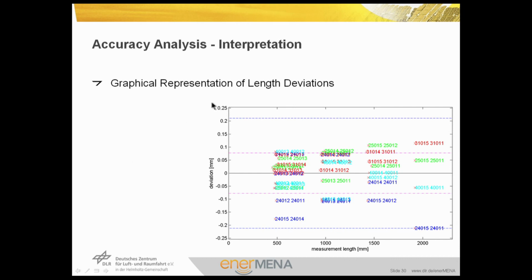The graphic on the lower right shows the distances for different points together with the mean and maximum value. So for the particular measurement shown here, the maximum deviation is in the range of 0.2 millimeter, so the overall measurement accuracy should be better than this value. You need an external macro programmed in a numerical software to obtain these deviations from the 3D data delivered by the AICON software.